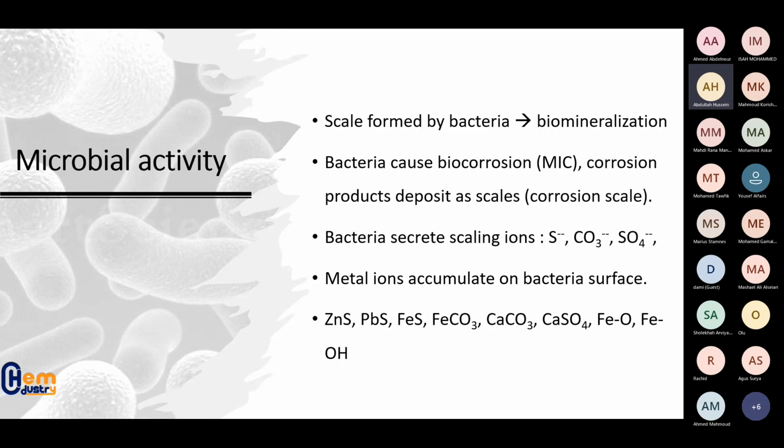There is a case that I was involved in where iron carbonate was the main scale problem, and we kept looking into everything in the system. We looked at the CO2 partial pressure. It was very low. We suspected that it might cause sweet corrosion, and then this would be a corrosion product. We looked into everything. We looked at the bicarbonate and the carbonate species in the water, and that was very low. And eventually we found that it was bacterial activity.